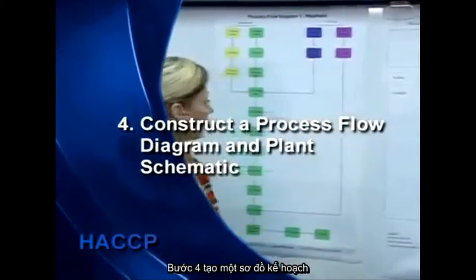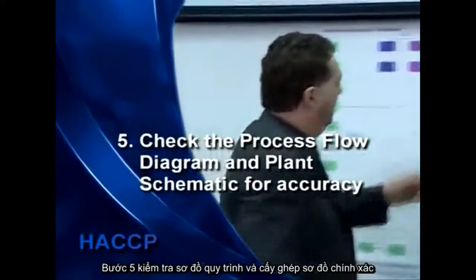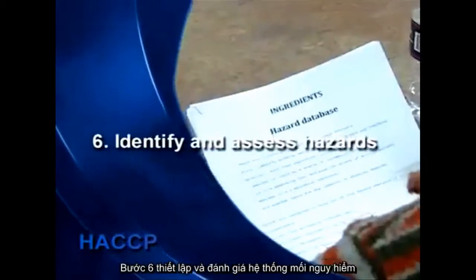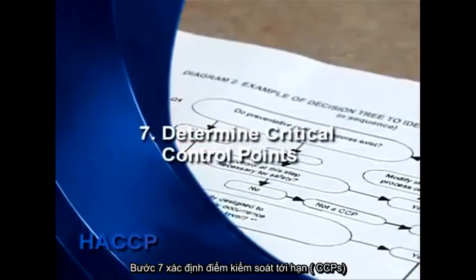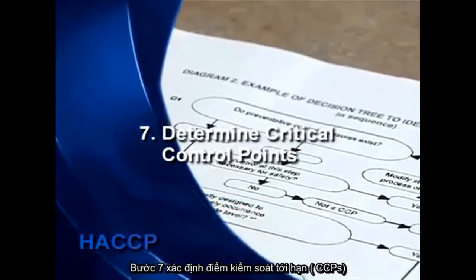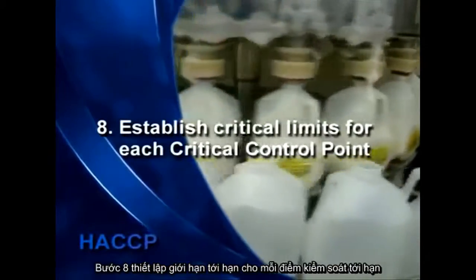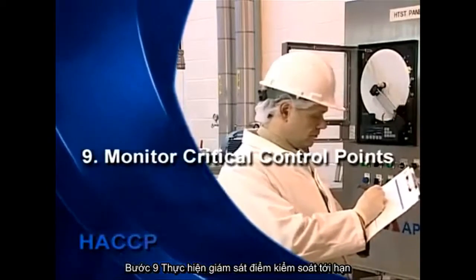Step 4. Construct a process flow diagram and plant schematic. Step 5. Check the process flow diagram and plant schematic for accuracy. Step 6. Identify and assess hazards. Step 7. Determine critical control points. Step 8. Establish critical limits for each critical control point. Step 9. Monitor critical control points.